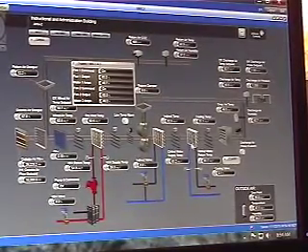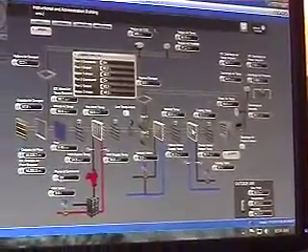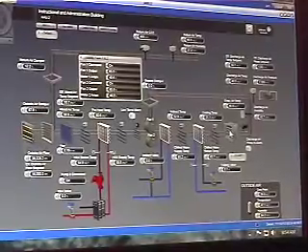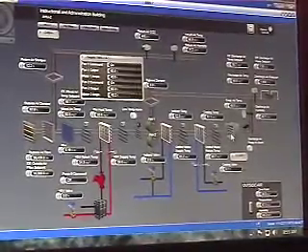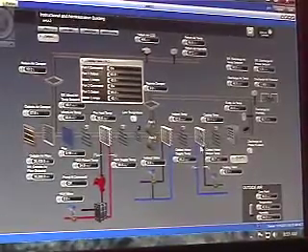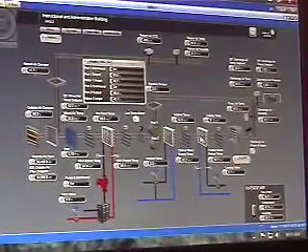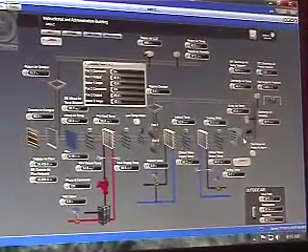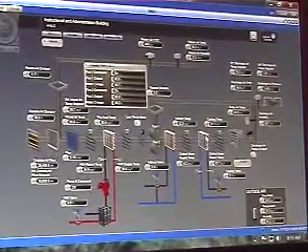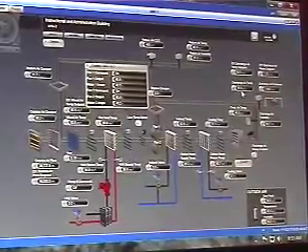From there, this one has a 30-minute run time. If we're still above set point, we then call for the direct or mechanical cooling, which will allow the chilled water system to modulate, to run right here. From here, the indirect coil is fully open, the evap media is running, and this is your controlling sensor right here to maintain this discharge air temperature.